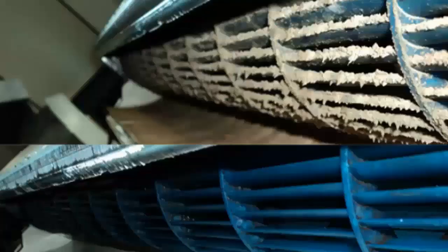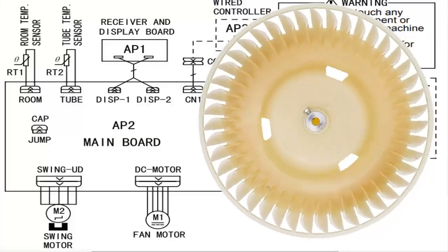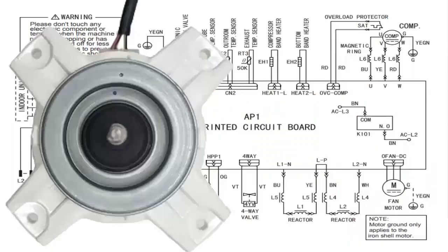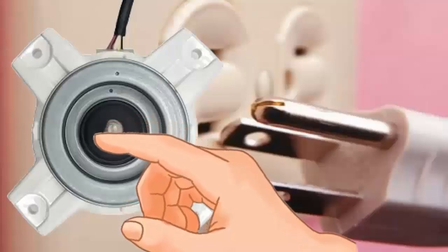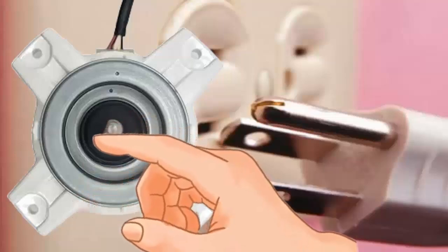3. If the fan motor is dirty, it may not rotate properly. 4. If the power cable is loose or damaged, it should be repaired or replaced. If the electrical connections are faulty, they should be cleaned or repaired. 5. If the fan does not rotate freely by hand, when the unit is powered off and without any noise, the problem may be with the fan bearings.